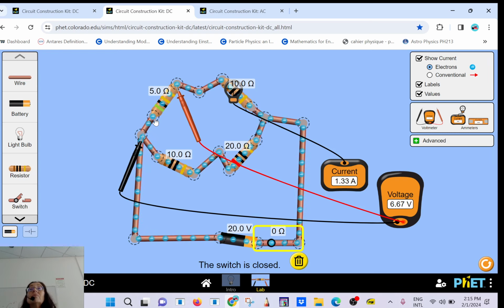Is that clear? So if I ask you for the test, if you go to Europe and the frequency is 50 hertz, which it is, how do you find the period? 1 over 50, okay? So AC doesn't work the same way. Plus in Europe, the RMS is 220 volt. Here, the RMS is 120 volt.